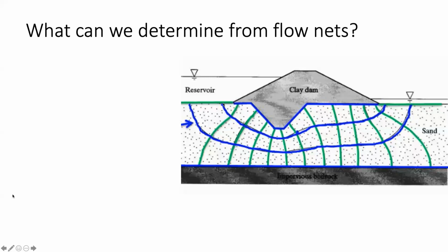Then when forming the boxes that we're trying for, these kinds of squares, and you can see they're not perfect, but these are pretty decent squares, you draw in your flow lines. So here are your flow lines in the system. And then between each of these flow lines, which are in blue, are going to be your flow channels.